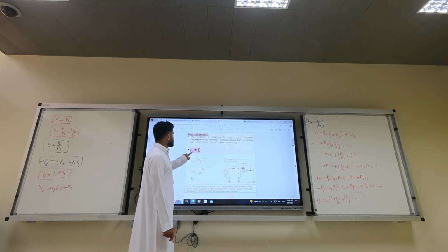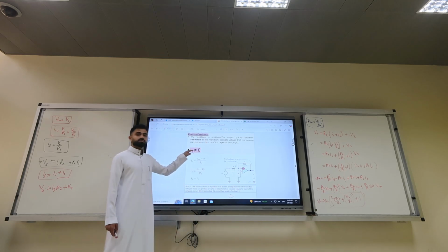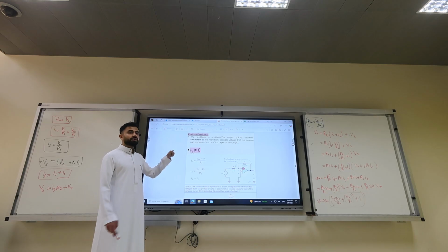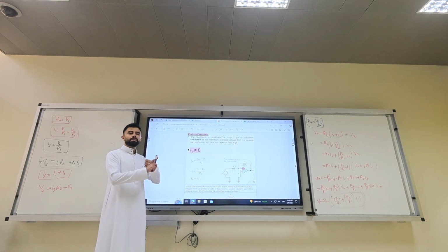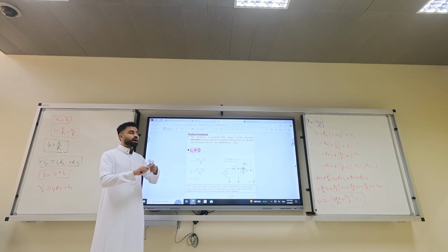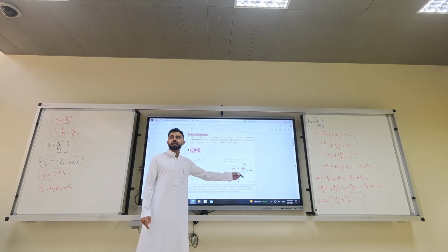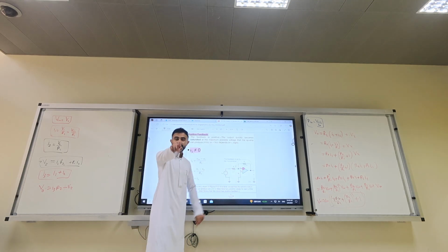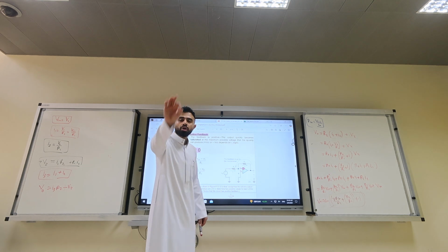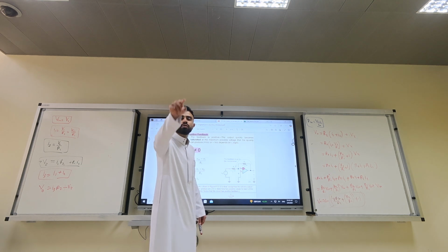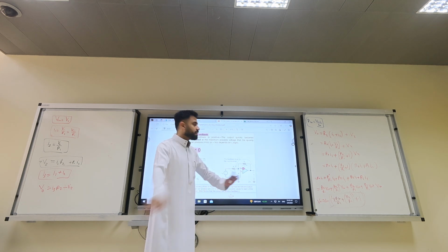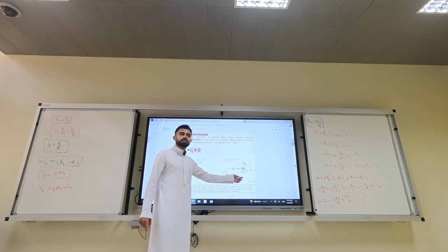So Vx is non-zero. Nobody, in a non-feedback amplifier or in a positive feedback amplifier, should say V positive equal to V negative. That's wrong. I'm going to repeat again. Only V positive equal to V negative when we have a negative feedback. Everything else, like the positive feedback, it's not true.